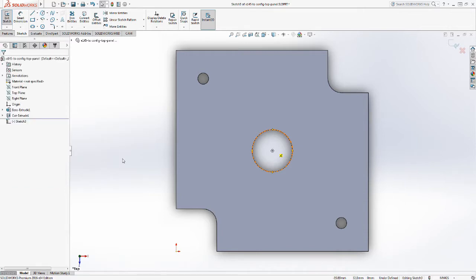And now anyone who knows anything about SolidWorks knows that you're not supposed to have these closed circles or circles that don't have any real definition. It's known as under-defining or over-defining. In this case of tracing, we're not going to run into that problem because essentially our CNC tool is just going to trace the lines that we have on the sketch here. So there we have the circle for our takeoff config button. And now let's go ahead and get into the text.